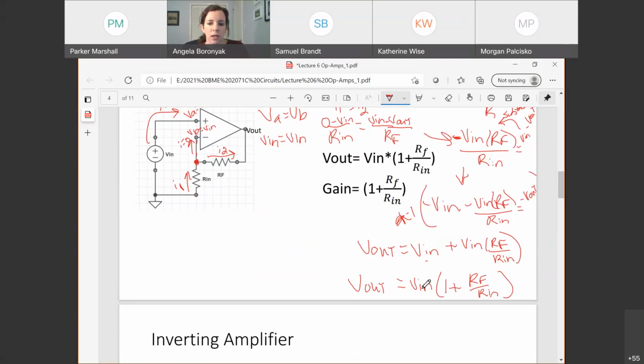It took a voltage in and it multiplies it, right? This whole thing is then multiplied, or you could write a big multiplied symbol here, by what? By 1 plus the ratio of RF, the feedback resistor because it went from my output to my inverting input, over Rn, which was kind of an input resistor because it went into our inverting input.